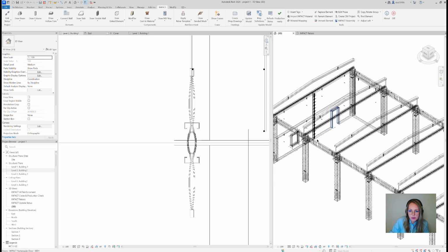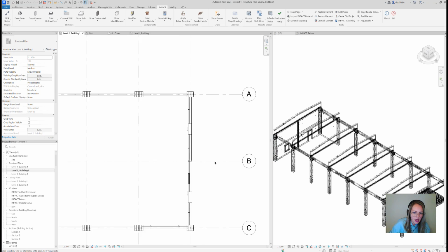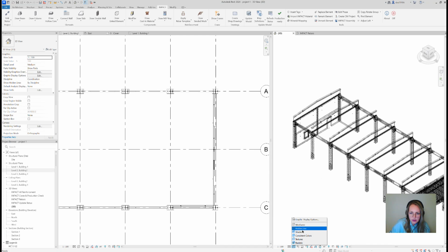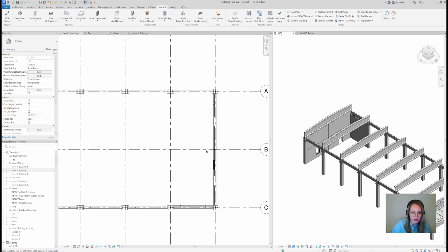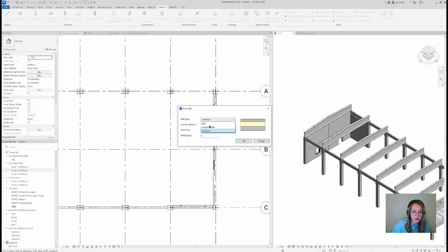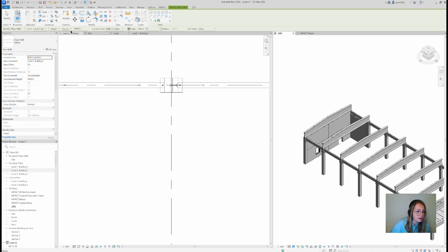Okay, what we're doing now is we're going to do some solid walls, panel thickenings, and slabs on top. So let's get moving. I'm going to do some solid walls, and in order to do a solid wall, you need to use again the draw wall command. And I'm going to say draw wall and use the wall I have a definition for. No gap intentionally again.